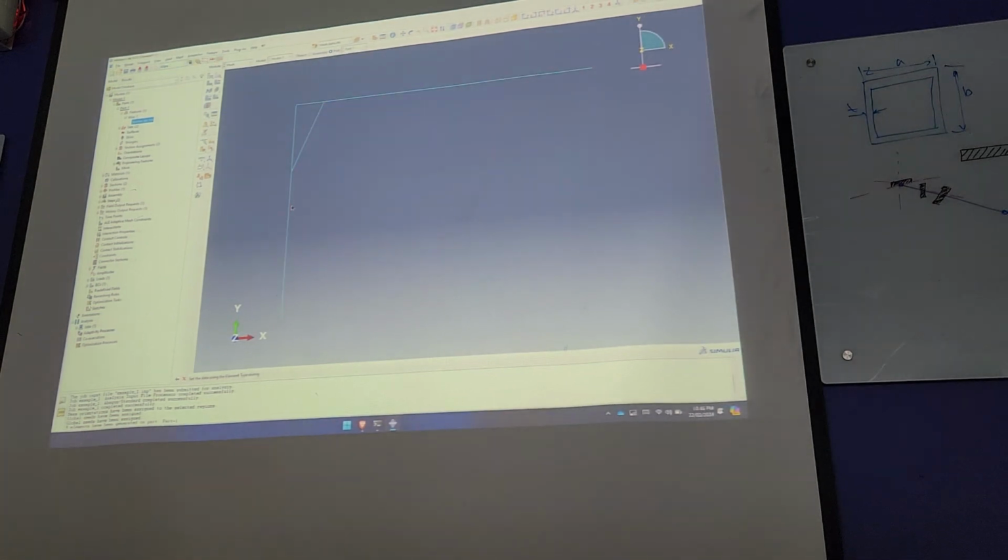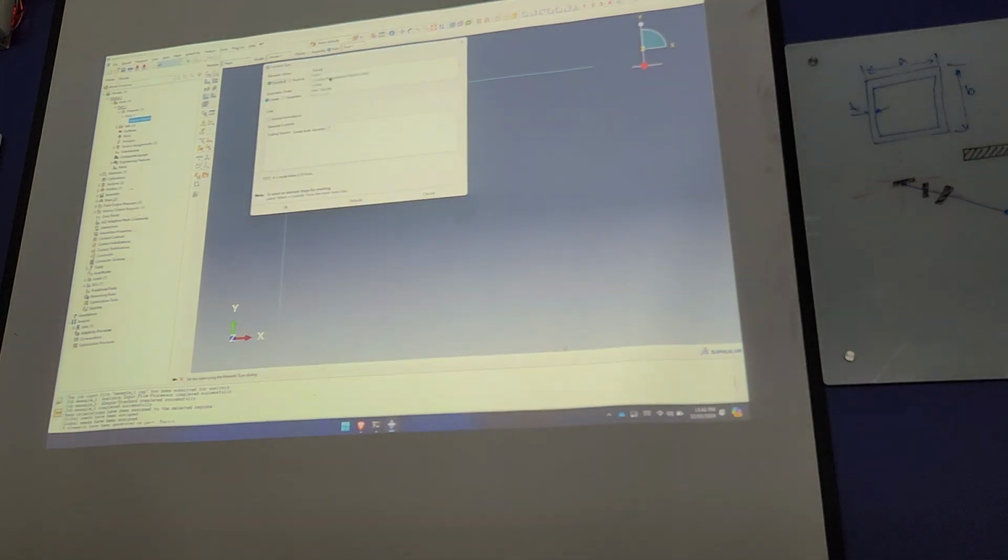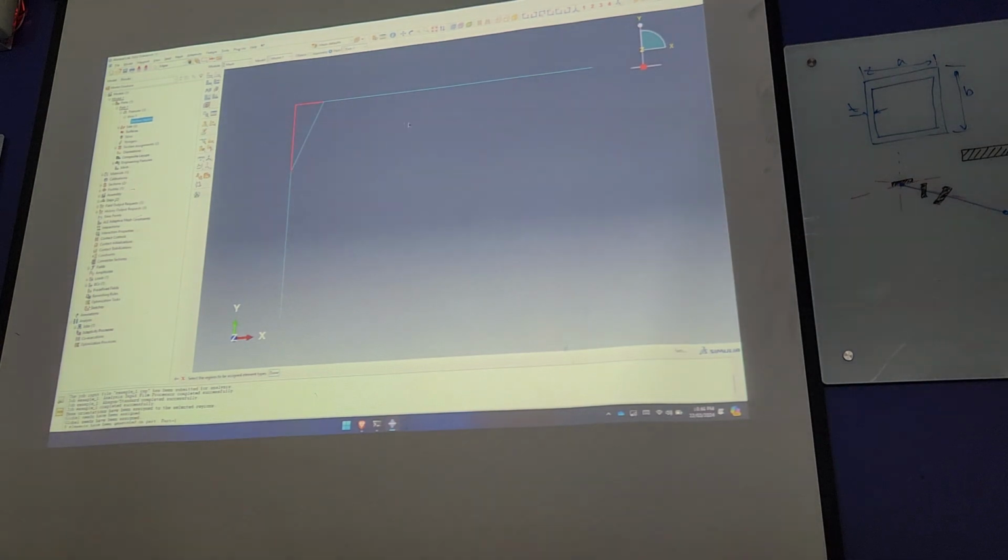So that's that. Now we go and change our truss. You click on that, done. Instead of choosing beam, you find your truss element. Yeah? And you say okay. Now we have beam there, there, and there, and here we have truss.